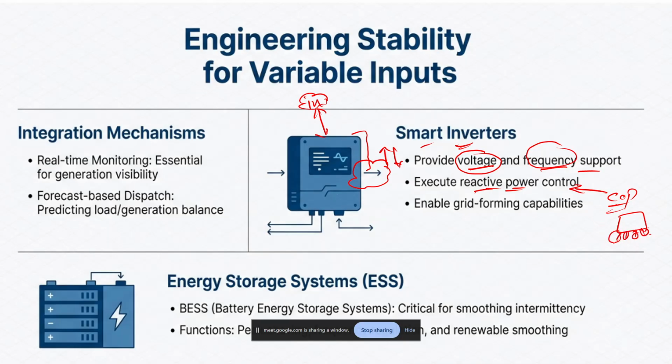These variable inputs can compensate the reactive power, depending on the quantity of injection of the reactive power needed. This can also be made automated based on these smart inverters. When we have everything in place, we can create the smart capability. This is one of the important things the smart inverters give us.